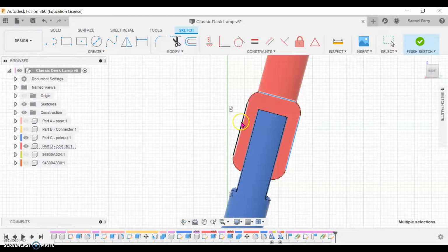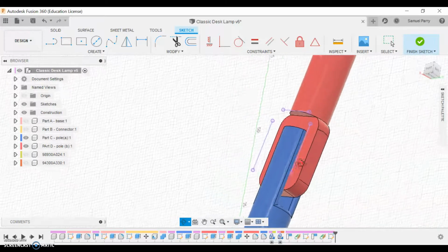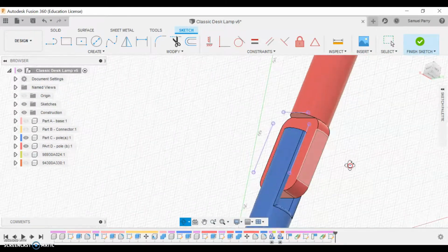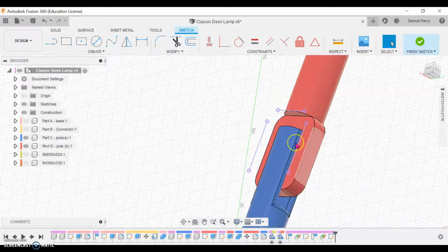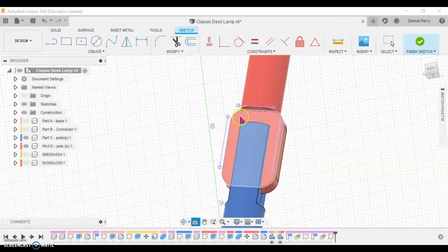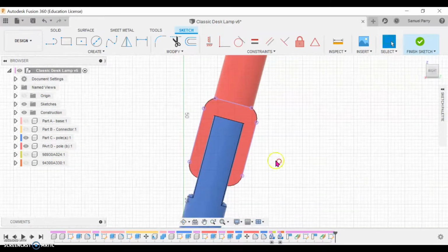So I'm just going to take these three lines and use them as a point of reference. Then I'm going to press return, and if I tilt now, you'll see that those lines have projected onto my new sketch, which is on this work plane, this tangent plane, and they give me a good point of reference. So what I'm going to do now is look at that face, so I'll get it all flattened in front of me.